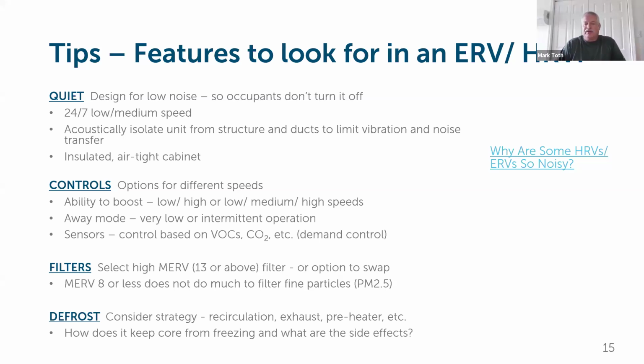But CO2 for an entire home, a regular house, would not normally be a good way to do it, because you need to ventilate for a lot of other reasons besides CO2. And you may never reach the CO2 level to trigger that sensor, depending on how the home is being used, how many people are there, how long they're there for, that sort of thing. Also, there's a lot of things about motion sensors that are good and bad, but we'll get into that as